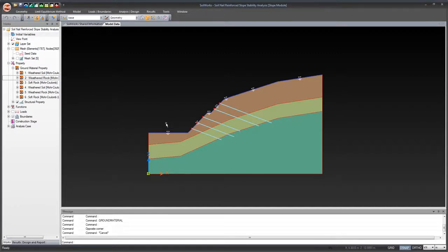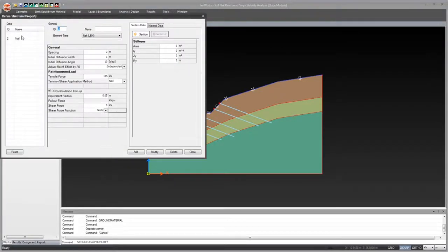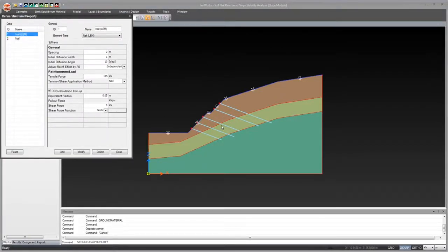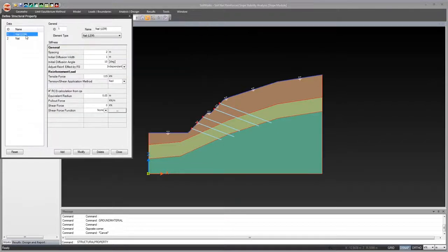Anyway, let's focus on the limit equilibrium method for now. Let's say, for example, I have my slope drawn here and I have all my material parameters assigned. By the way, these lines over here represent tiebacks that have been installed to keep the slope more stable, and material properties can be found for those as well. I have LEM properties for the soil nails or the tiebacks, as well as finite element properties. If I go here, I still need the modulus of elasticity, the Poisson's ratio, etc., and yield strength. Whereas if I go to the limit equilibrium method, it's a much smaller set of parameters.